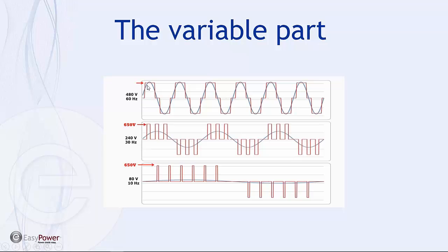The energy that's delivered to the motor is actually the average integral under the pulses, which will approximate a sine wave, and that's how the motors are controlled. And so we're left with a couple of different trade-offs when we start talking about VFDs.